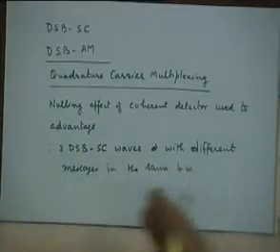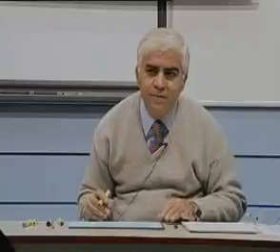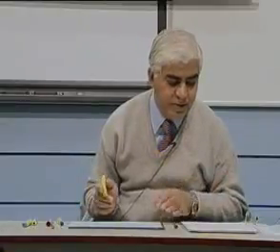The spectral occupancy of both the modulated signals will be in the same fc plus or minus B hertz, right? So if you can do that, what would you do? You would increase your bandwidth efficiency by a factor of 2. In the same bandwidth where you were transmitting only one message, now you are transmitting two messages.